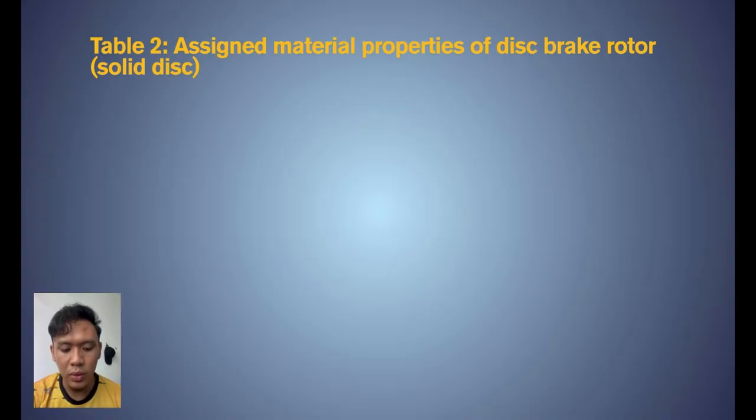As we increase the load to 2000 Newton, the stress rose slightly to 1.41 times 10 to the power of 6 Newton per meter squared. Finally, at 4,000 Newton, the maximum stress reached 1.57 times 10 to the power of 6 Newton per meter squared. Throughout this test, the translation displacement remained extremely low, peaking at only 0.000451 millimeter under the highest load, indicating high structural rigidity.